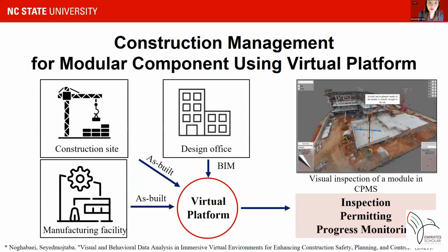To overcome these issues, our idea is to use a visual construction management framework. There is recent research on a visual management platform called CPMS, Construction Performance Modeling and Simulation. CPMS is capable of comparison between the BIM and the reality model, as well as between different reality models. Such a virtual environment allows inspection between the construction and design model, and also between two reality models for adjoining parts of the modules. This can manage the potential risk by checking in a virtual environment before delivery.